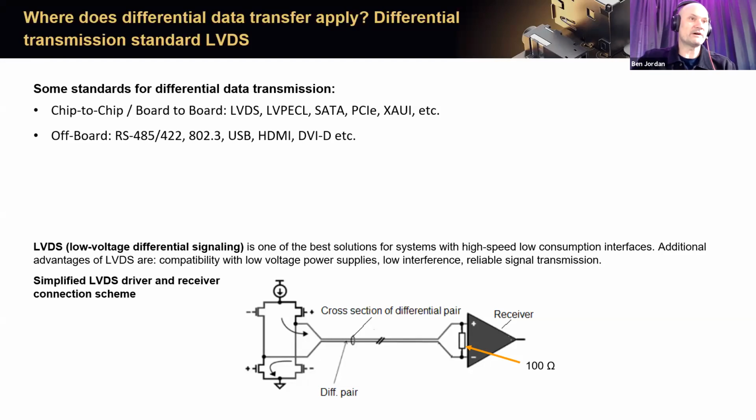And you're all pretty familiar with those. So one other thing, just with this diagram here, the circuit diagram at the bottom showing the receiver, I mentioned in the last slide that typically our inputs are MOSFET gates. And so those are capacitive loads that have no DC path, and they're usually pretty high impedance.